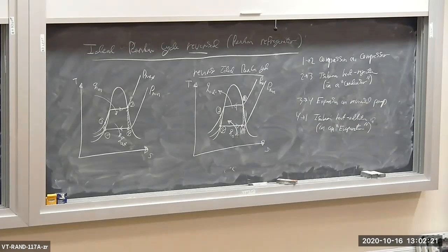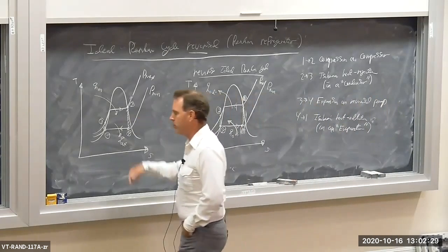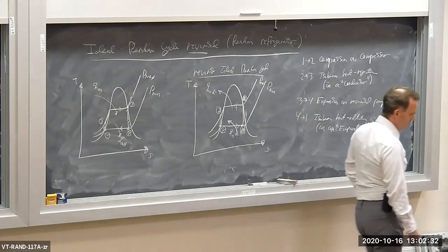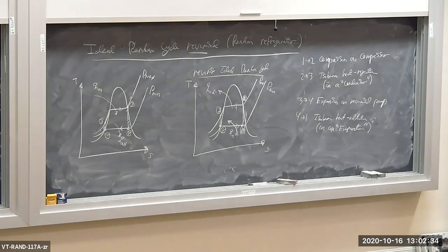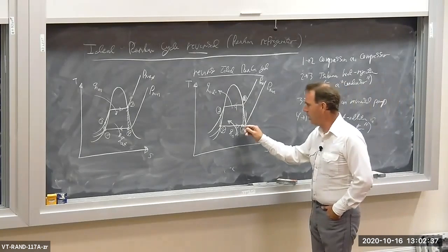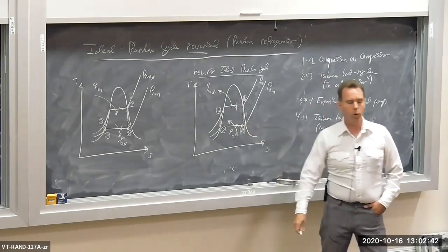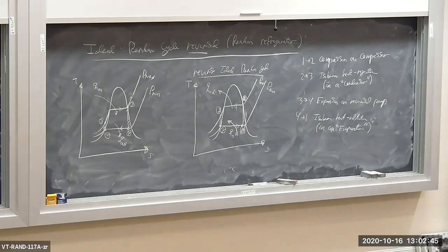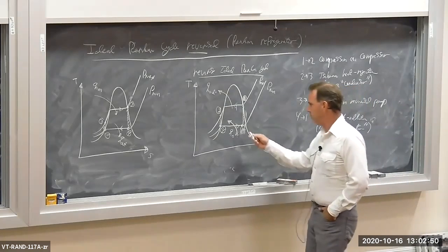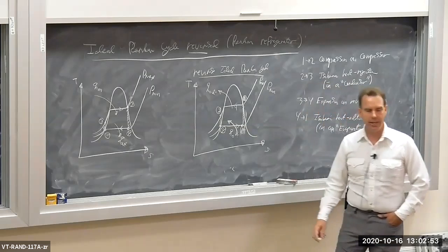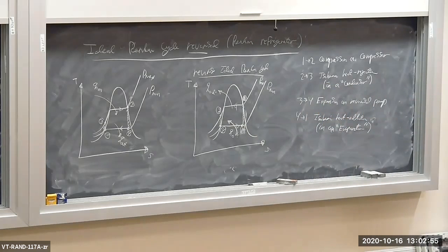Now, there are a couple of problems with this envisioned reversed ideal Rankine cycle, just like there were some problems with the Rankine cycle. The big problem is that compressors, just like turbines, really don't like working with liquid in the fluid. Compressors like a gas to compress. If you mix droplets of condensed liquid into a gas being compressed, it's going to cause significant damage to the compressor.